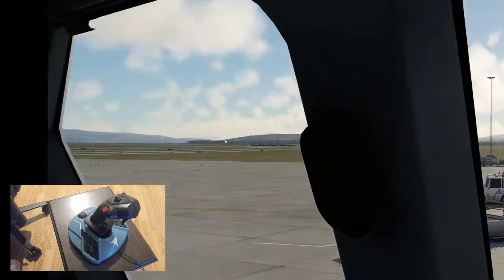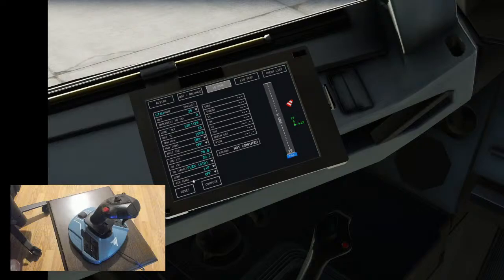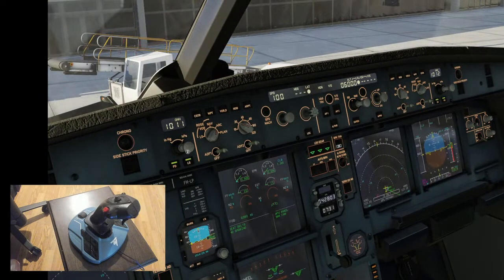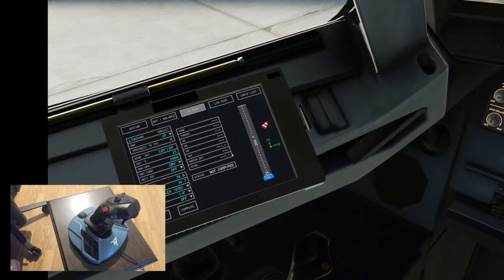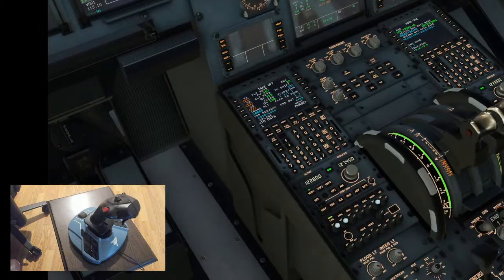Today we are expecting partially cloudy weather in Kayseri and in arrival. And our local QNH 1008. For both sides, captain side and the FO side, we are inserting those values. And then we continue. I'm computing here. Yes, our critical speed, flex 30 and thrust 1 down 0.7. Flex 30. It seems that we are ready.